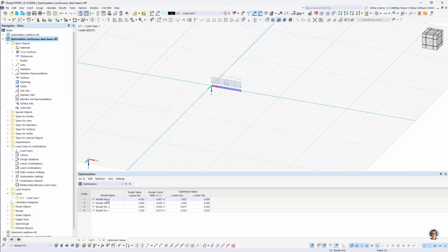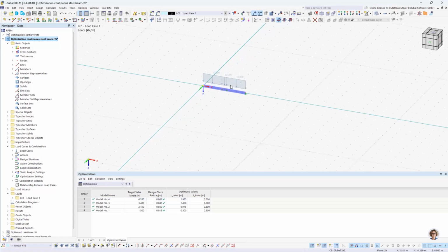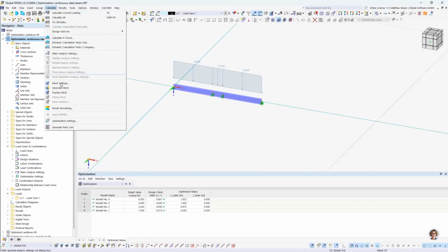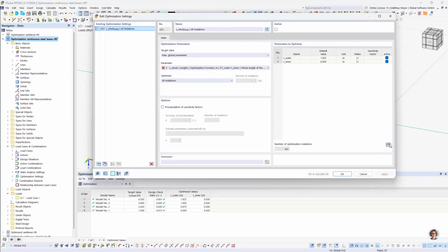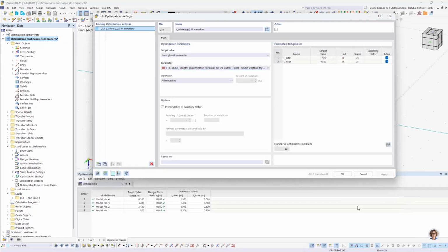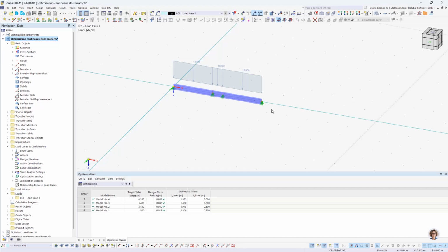Okay, and if you cancel the optimization procedure, it will take the last optimum it could find and will set all our parameters to this last optimum. So it's set to 1.925 and 0.5, and uses this also for our model.